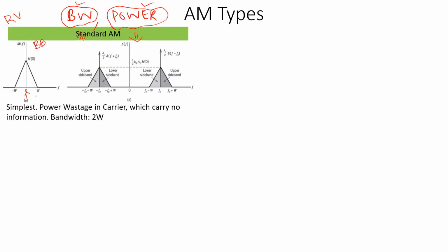And this is the spectrum of our modulated signal. You can see that the modulated signal spectrum is nothing but the message signal spectrum shifted, or frequency translated, to plus FC and minus FC. In the positive frequency part, the negative part of the message spectrum is also visible here. We will discuss the significance of negative frequencies later. So basically after modulation the frequency is translated.